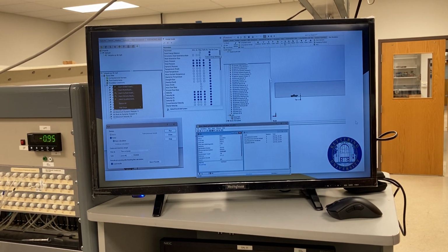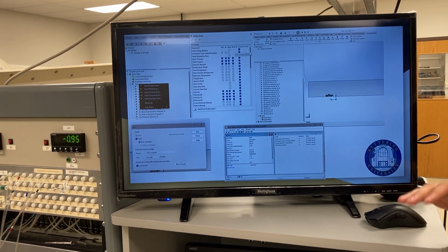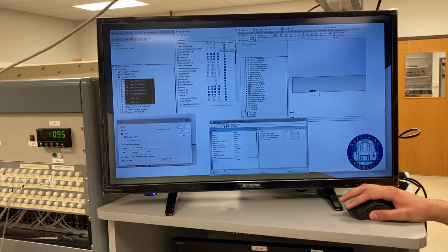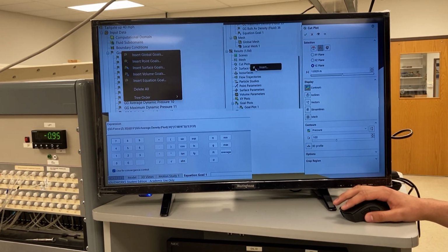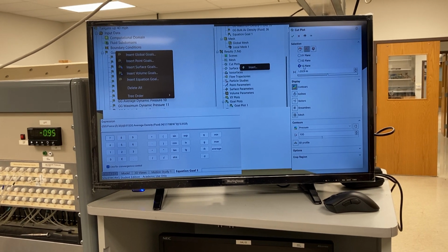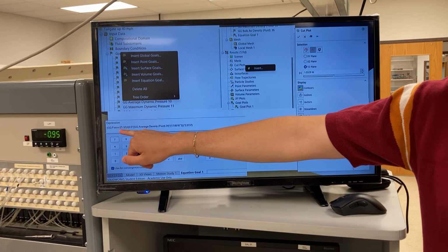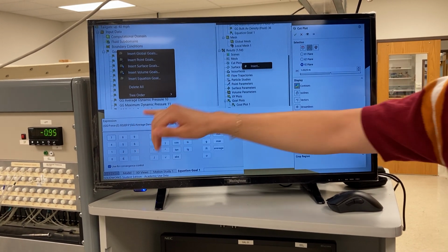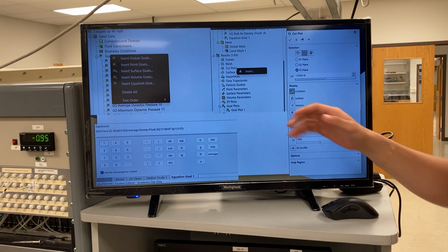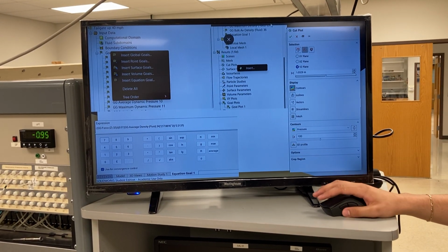We selected all our important pressures, velocities, densities, and then you can run the simulation after selecting what values you wanted to give you. We also had to insert a calculation for the drag coefficient since the software didn't calculate it. So we used our force in the z direction, which is our drag. We used our average density of the fluid within the computational domain as our density, since it would change in different places, and our velocities that we were running the air at.